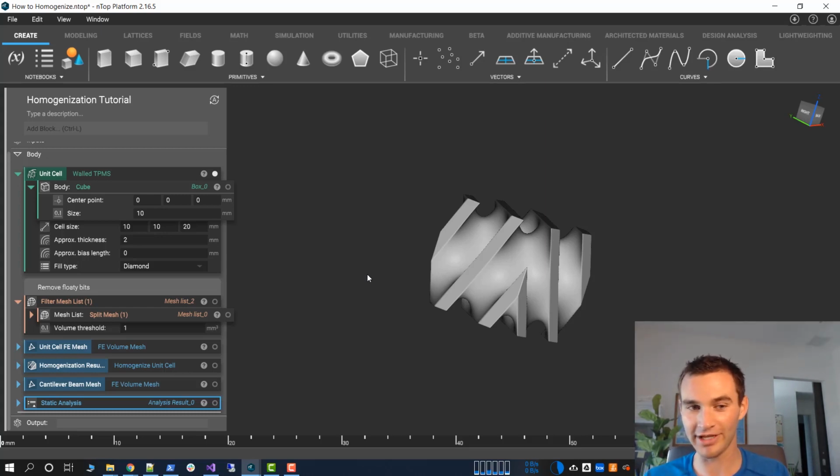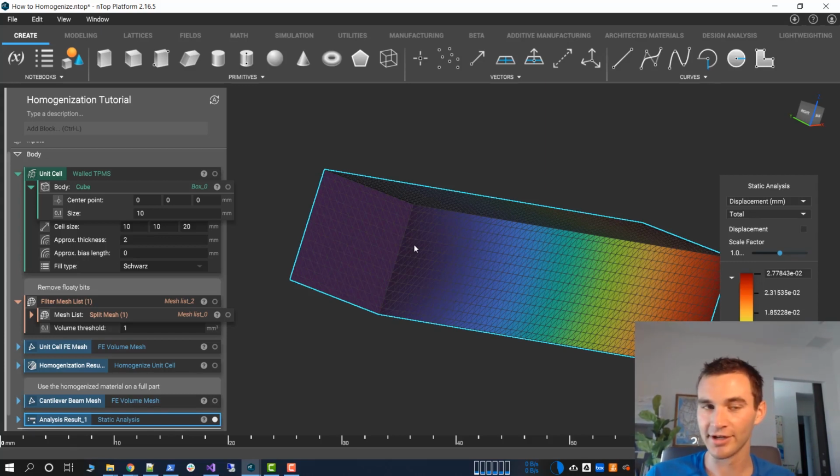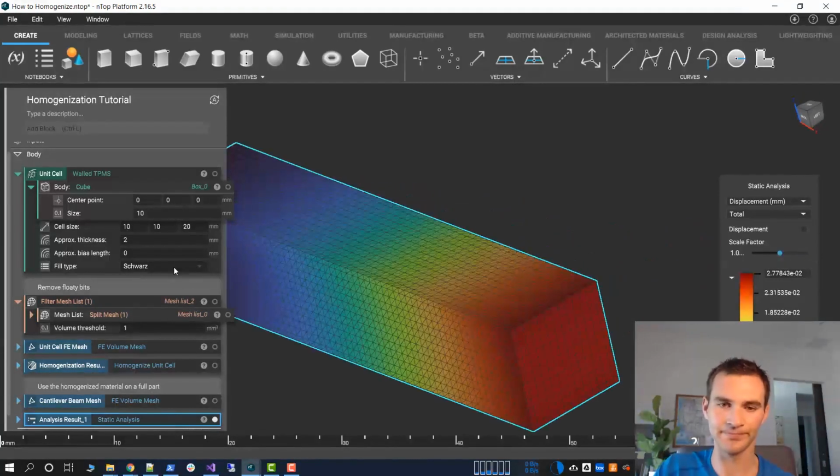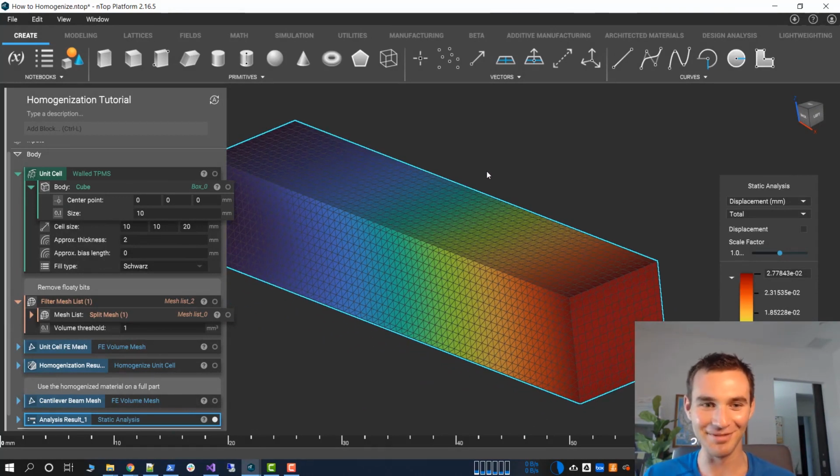There's a lot more cool things you can do with homogenization, which I would say stay tuned for. So things like electrical and thermal properties, some of those can be homogenized, so you can start to do this type of analysis with multiphysics, which is pretty exciting. So you're designing on an Ashby chart, not just of stiffness and density, but also thermal conductivity and stuff like that. So there's really a lot of potential with this technique, but again, I have to mention the limitation is how many unit cells do you have?